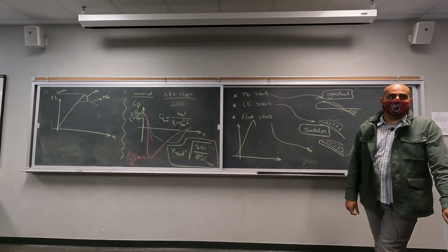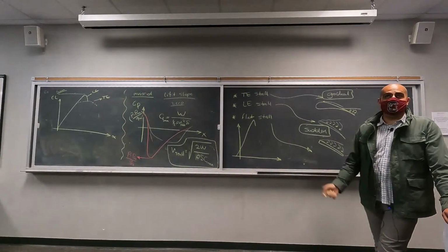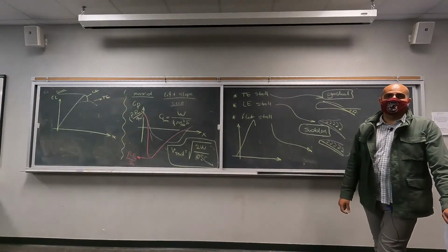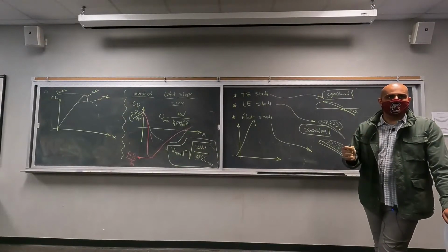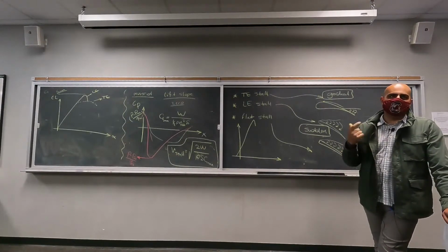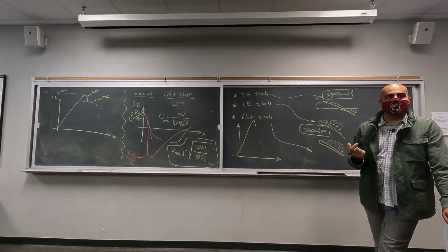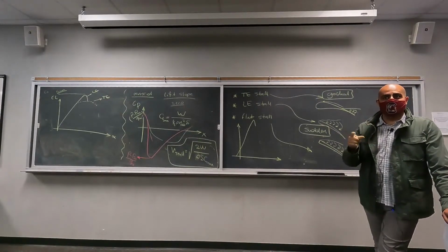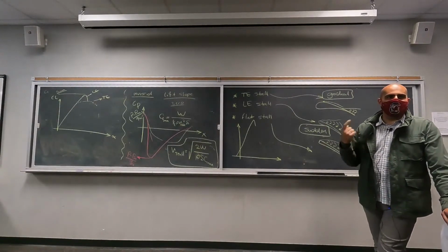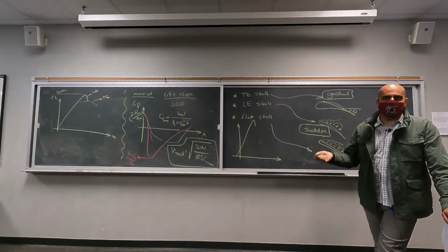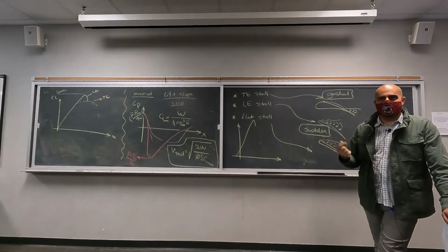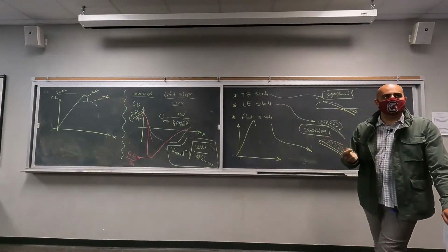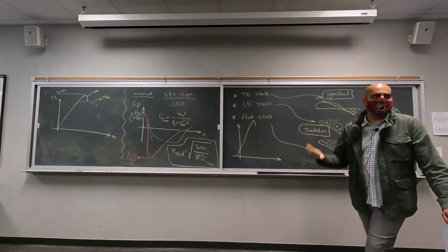Sharp edges, right? What do sharp edges do? They are going to facilitate the separation, right? So the separation doesn't really happen... I mean, it happens because of the adverse pressure gradient, but your sharp edges, sharp corners are going to be helping the flow separation. You know, we had a discussion about tipping the flow to turbulence, right? So you have some sort of a mechanism there on your airfoil to tip the flow. These sharp corners are tipping the flow to separation, if you will, okay?